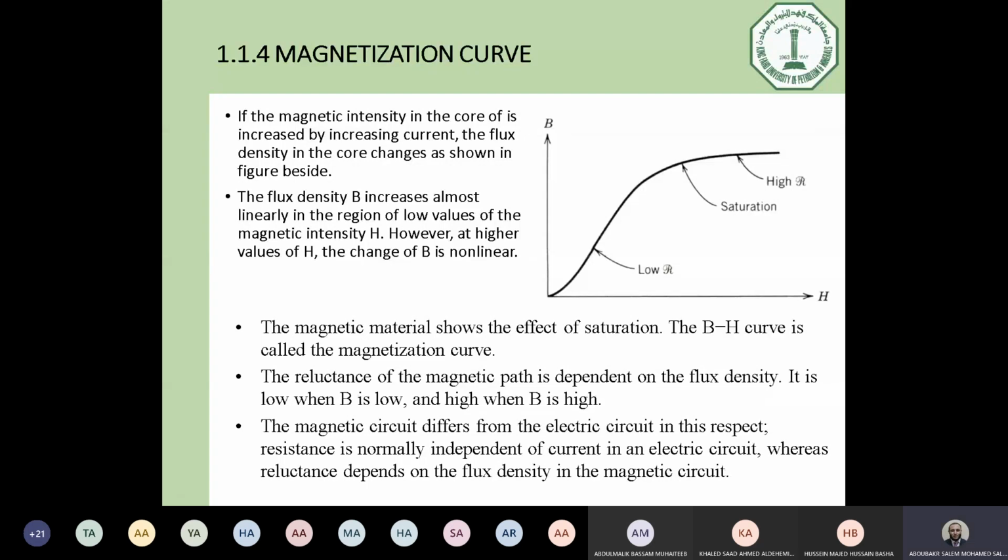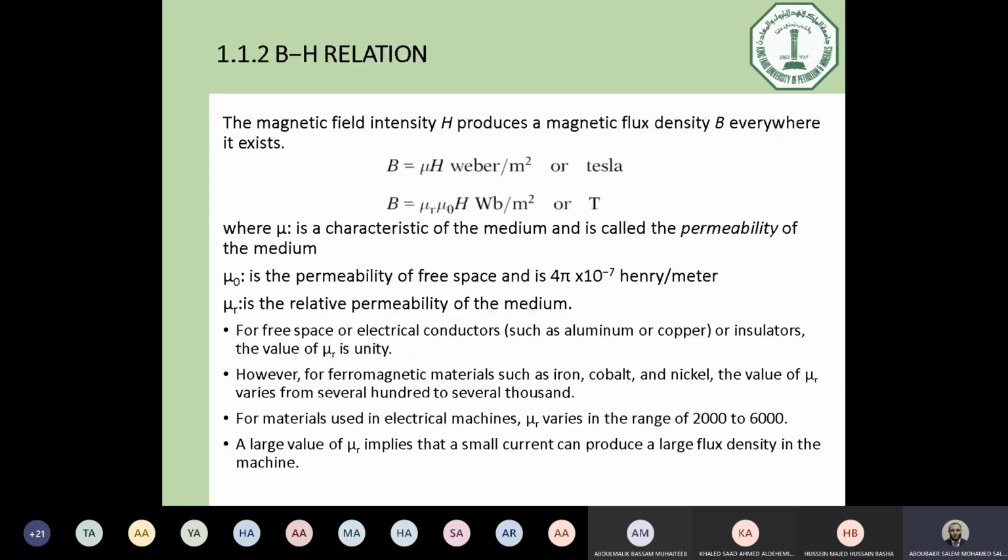I don't like to confuse you, but you have to recognize the difference: we should select material of high permeability. However, it's not correct to work at the value of high permeability of the core itself. Again, these are two different things. When you select magnetic material, it's better to select material of high permeability, like what we already compared in the previous slides here.